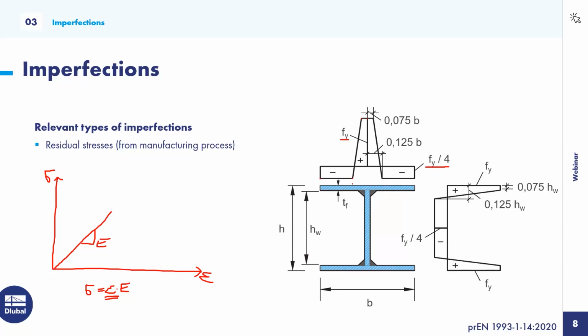So we have to divide our flange plates into parts that are suitable for this actual strain definition. So for example, we can divide the flange plate here and there. I try to draw this as accurately as possible. So we have one constant block here, one constant block here, and in between one linear part. And that's exactly what I have already done in a separate file, so that I want to show you now.